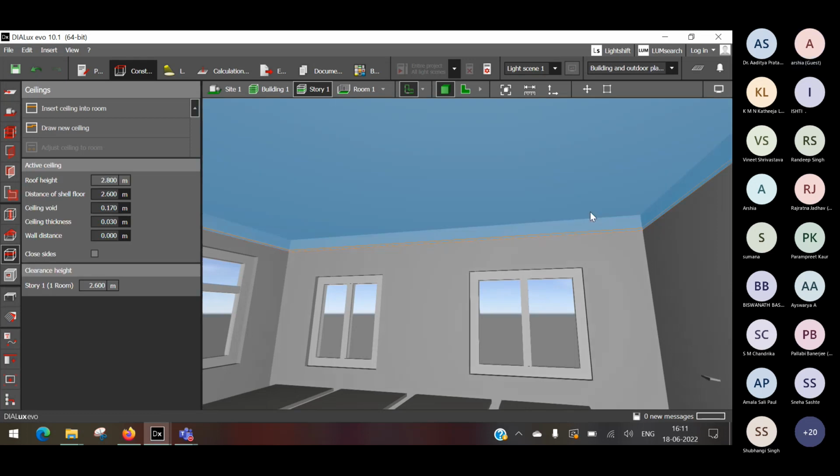Right, right. So now here you can see I removed that earlier ceiling. Ceiling actually reduces the height of the room, thereby your requirement of light can be controlled also. It has its own values, but if you have a larger room and the window size is still the same, then of course you have a larger space to illuminate and your overall uniformity factor reduces, and therefore bringing in a ceiling has its own advantages.